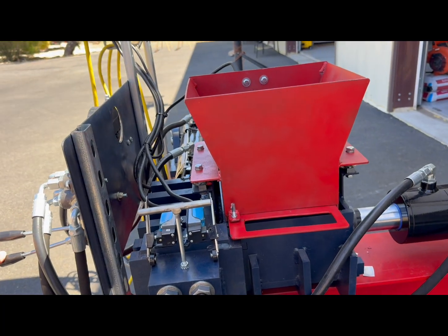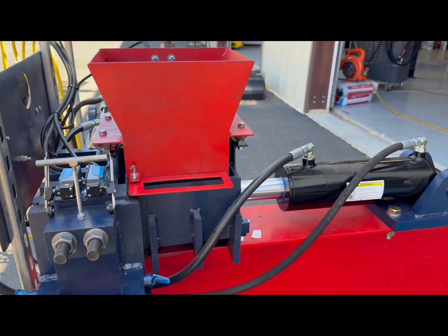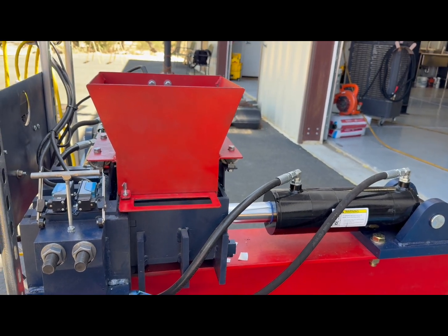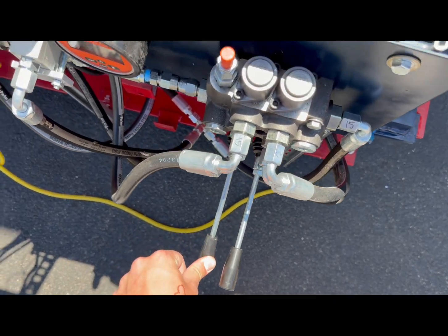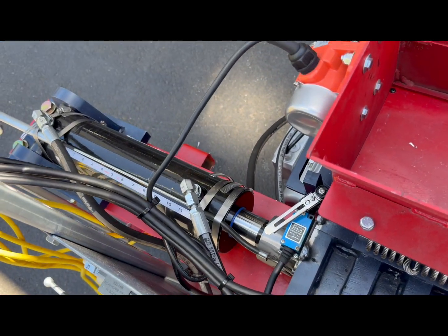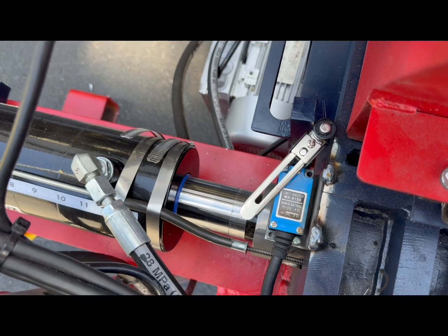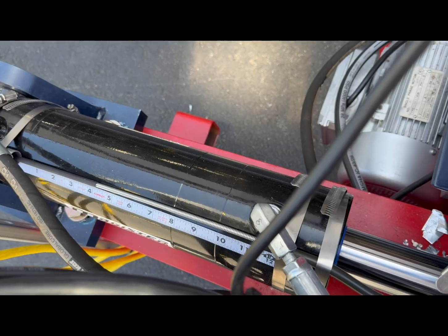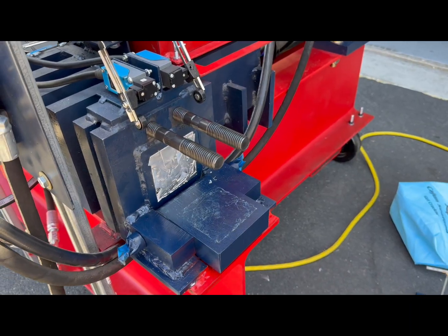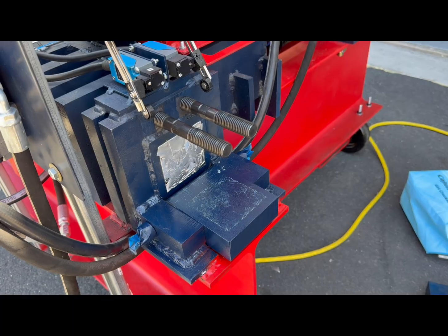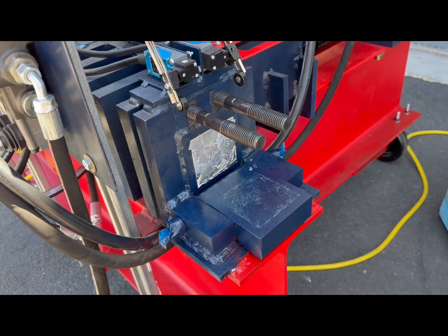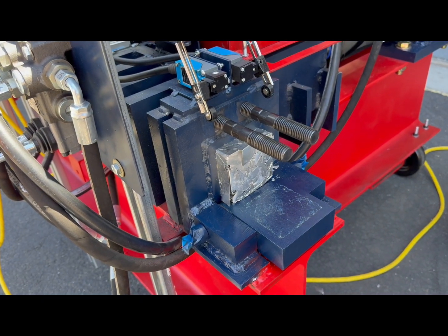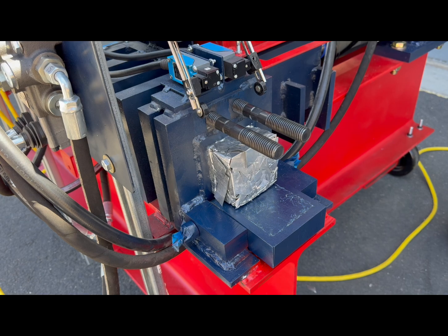Once the material is positioned, we begin the first stage of compression. This initial compression reduces large air pockets and begins forming the shape of the bale. After that, we move into the second stage of compression, where a much higher pressure is applied. This step further compacts the material and creates a dense, uniform bale. Finally, we remove the ejection door and the completed bale is pushed out of the chamber. This process demonstrates how pre-processing and staged compression work together to significantly improve material packing and overall bale density.